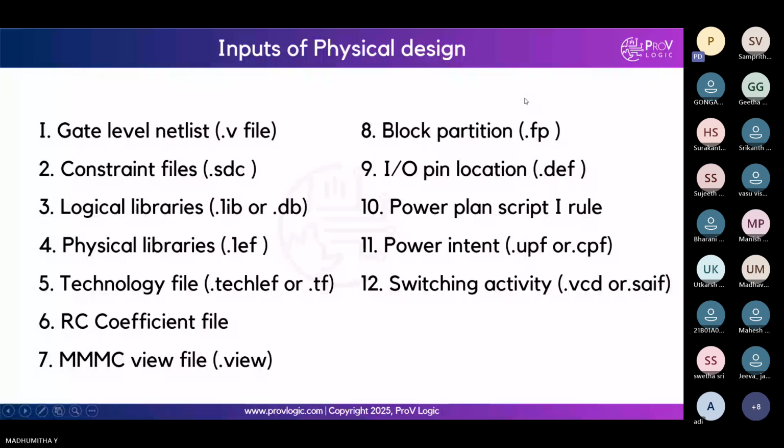In this constraint file, all the timing constraints, power constraints, and area constraints specified by the client will be mentioned. This constraint file will be generated by the top level team. For example, if we are going to design an IC, top level engineers or senior engineers will create this SDC file. An entry level physical design engineer will not work on an SDC file; they will get it as an input. As you gain experience, like 3, 5, or 7 years, depending upon your expertise and talent, you can start designing this SDC file.